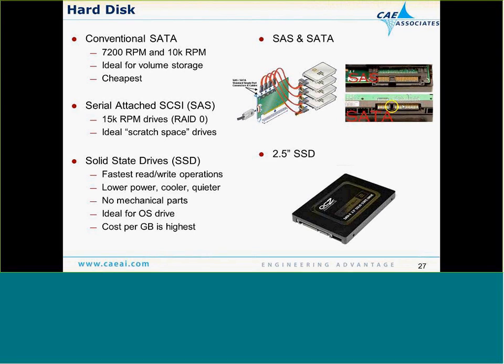So the direction that we go at CAE Associates is we tend to build our computers with a volume that's serial attached SCSI, striped in a RAID 0 fashion. ANSYS Mechanical will see a huge benefit from this. You run much faster. As I mentioned before, it's intensive I/O. The catch-22 here is if you happen to be running on a distributed memory, multiple node cluster, you actually could benefit even more if you ran your drives in a Lustre environment. It's a Lustre-mounted volume where it enables parallel I/O. But for single node applications, definitely you want to try to go serial attached SCSI.